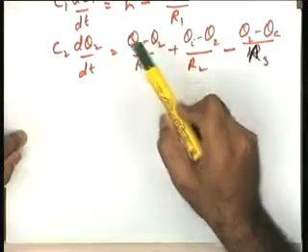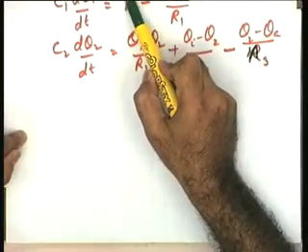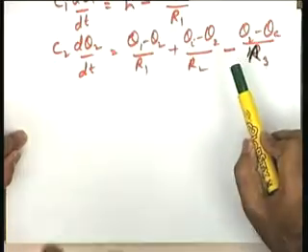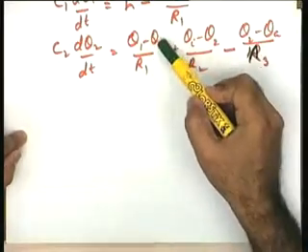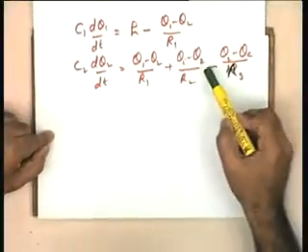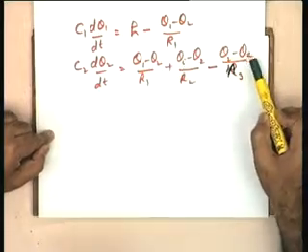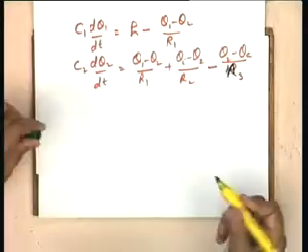You will have to first ask a question as to transfer function. For the transfer function, what attribute of the system am I interested in? Maybe I am interested in theta 2 as the output variable and h as the input variable. In that particular case, I will get the transfer function between theta 2 and h, assuming theta I and theta a to be 0. This point is to be noted, please.